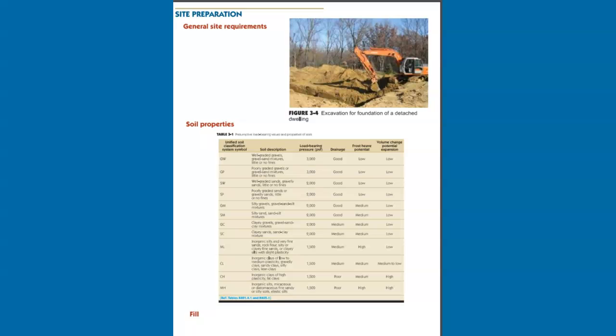Soil properties. The designer or builder must carefully consider soil properties not only for adequate support of the foundation but also for stability to prevent future damage to the structure. Based on experience and known local soil conditions, the building official will often permit design based on a presumptive load-bearing value without soil testing or a geotechnical report.